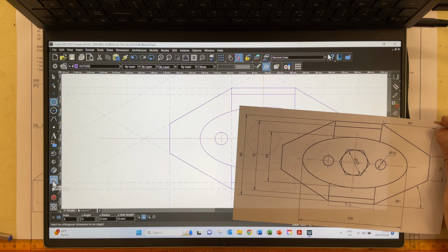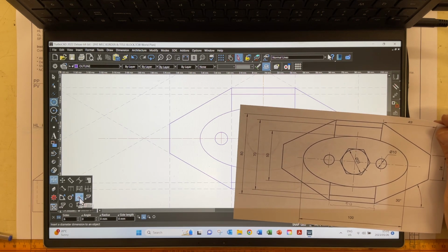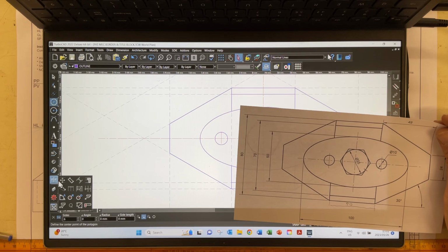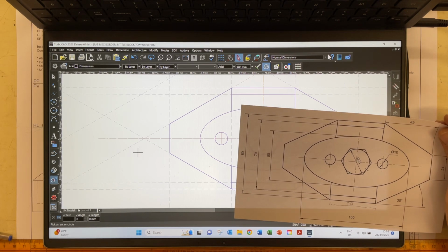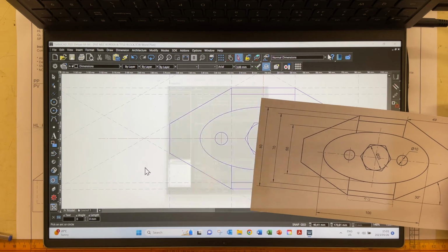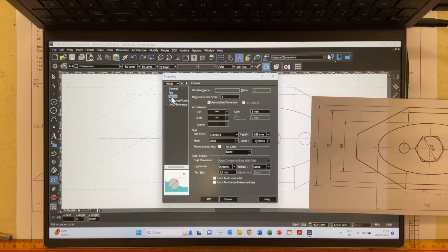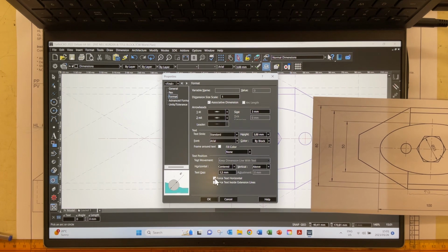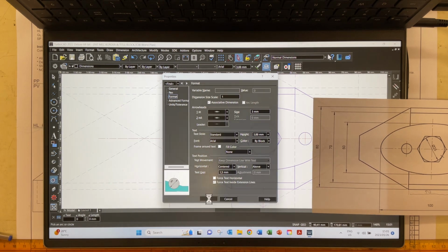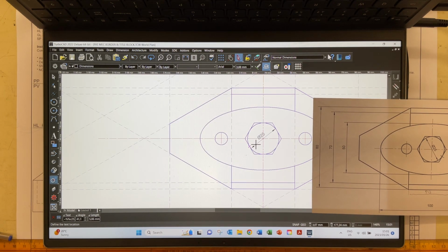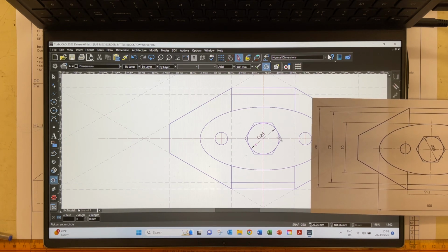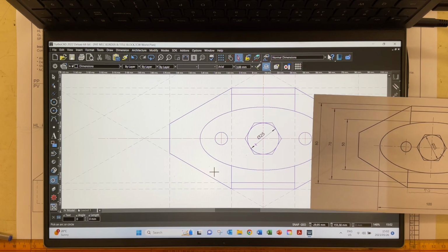You come in over here, do a nice long click on the diameter, on the orthogonal dimension thing, come down to diameters, do a nice right click there, go to properties. Go to format over here, unclick that little thing that says force text horizontal, say to it force text inside, and make sure that it says keep dimension line with text over there. Right, press OK, click on your diameter, and there you go, you've got a diameter little symbol over there, and the diameter of that circle drawn in on the inside of that circle.